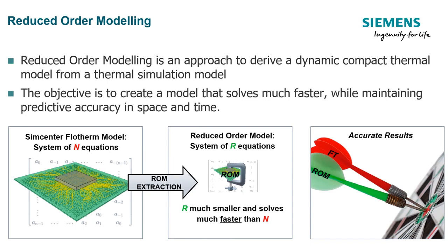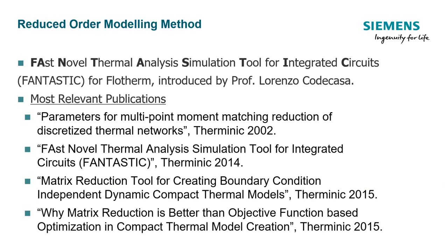A BCI-ROM will enable extremely fast transient solutions while retaining high accuracy in all situations. The BCI-ROM extraction method in Simcenter Flotherm is an extension of the fantastic method. For more information on this method, refer to the validation documents on Support Center and the following literature.